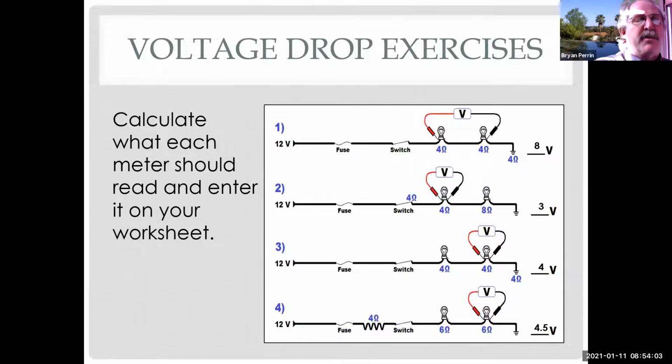Now I'm going to take that 3/4 or 0.75 and multiply it times the 6 ohms that my meter's reading across. So 0.75 times 6 is 4.5. Or if I want to divide 6 into 4 parts, each part would be 1.5. Right? So I got 3 1.5s, which is 4.5. A couple of different ways you can get there. Okay.